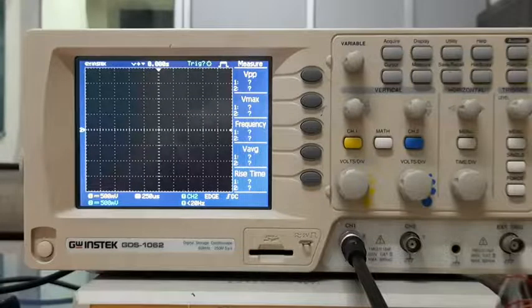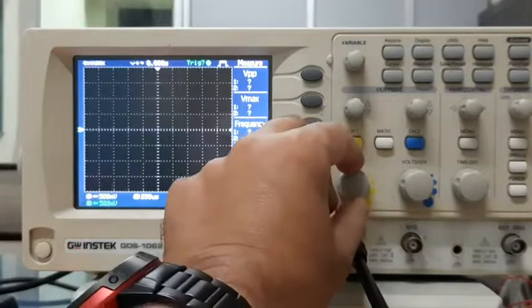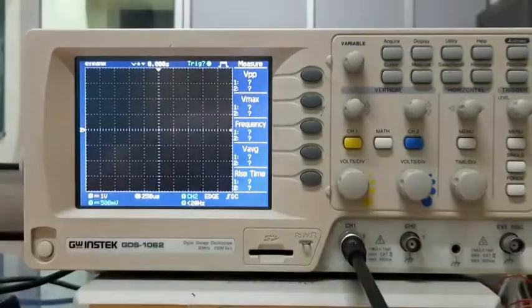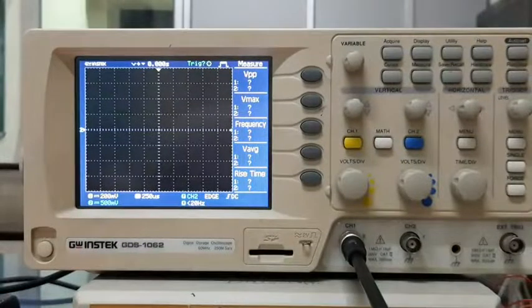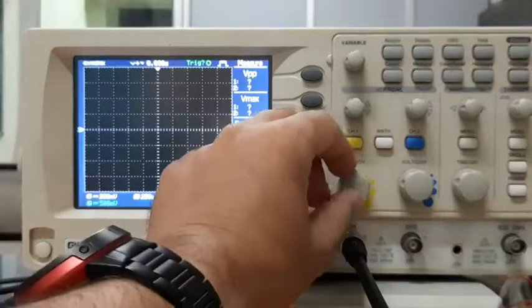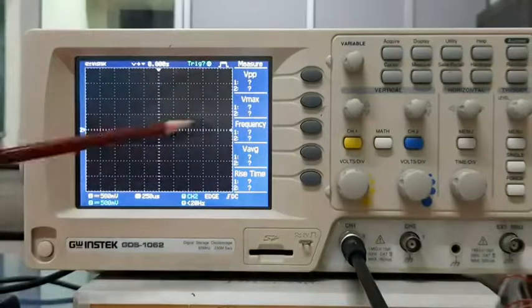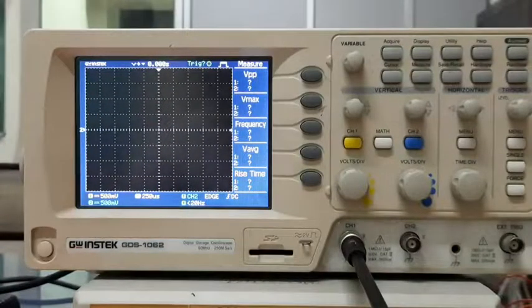We expect a signal amplitude of plus minus 1 volt on either side, right? So that means this scale, which is set at 500 millivolt, is probably okay. I can go lower by turning this clockwise or anti-clockwise. If I turn it anti-clockwise, then this goes to 1 volt. I can turn it anti-clockwise and then go to 200 millivolt. So I can change the range this way. But 500 millivolt seems fine, because overall, on the vertical side, the display gives me a total change of plus minus 2 volts, and a plus minus 1 volt signal can be easily seen on this.